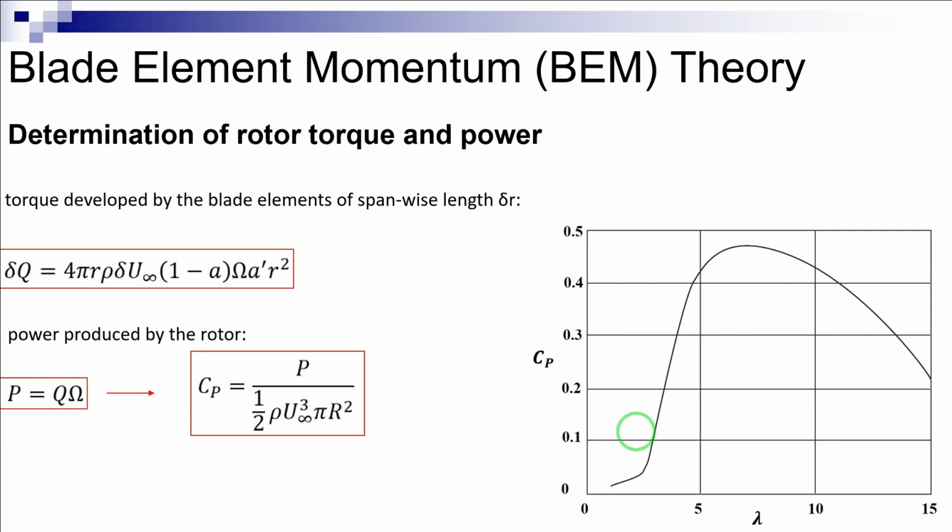As can be seen in this figure, over small values of tip speed ratio, there is a significant loss of power, which is attributed to blade stalling. Over both high and low tip speed ratios, drag is high and the axial induction factor is non-optimum, so the power coefficient is low. The optimum scenario would be for a turbine operating at a tip speed ratio close to that which gives the maximum power coefficient for all wind speeds.